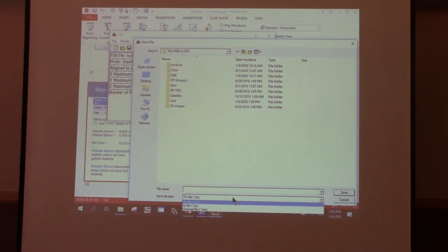There's really no easy way to do what you want to do. It's because there's so many nodes and faces. In a regular channel, you think about a channel, your one section might be 300 feet long or 1,000 feet long in a rectangle that is all one depth. It's 2 faces at most. In that same non-linear type of environmental dredging, you could have 50,000 faces. And it's just difficult to generate all those faces. That's why we did the matrix file method.